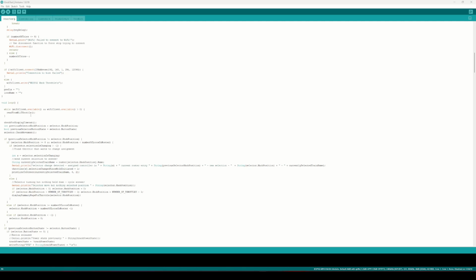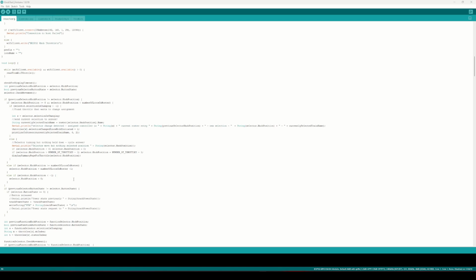Someone left a comment on the first video that there's a WiThrottle library for Arduino. I didn't know there was, so I've just written this kind of raw. So all of the communication with WiThrottle, whether that's sending updates to speed to actually drive trains or whatever, is done pretty raw with the TCP connection and just using the WiThrottle protocol, which to be honest is fairly simple.